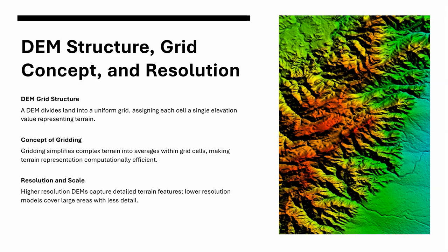And a key concept in a DEM is its resolution, the size of each grid cell. High-resolution DEMs may have cells every meter or smaller, and this captures lots of detail. Small ditches, gullies, even road cuts may appear. Coarse DEMs may have cell sizes of over 30 meters, and they're going to smooth over many of those details, capturing only large-scale features like ridges, valleys, and floodplains.